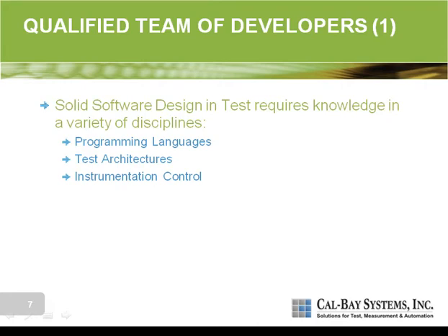You need to understand instrument control. So this might be GPIB, VXI, PXI, LXI, USB, RS-232. How do you talk to instruments? How do you send commands? How do you receive data? You need to understand databases and reporting tools. So when we're storing the results from our test, how do we store that data, and then how do we generate reports for engineers or managers? Obviously, we need to have DUT-specific knowledge, so we need to understand all of the specifics of what we're testing, the unit under test, and how to control it, and what the requirements are for testing it.